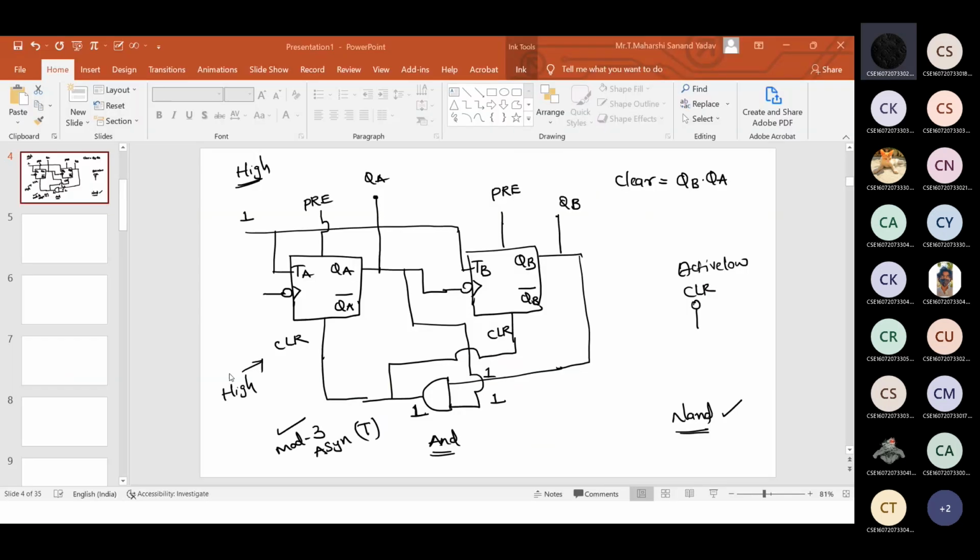So can you tell me the answer now for another question? Tell me the answer for 1000. Tell me logical left shift, logical right shift, arithmetic left shift and arithmetic right shift. Tell me the answers for 1000. Shift it only by 1-bit position.